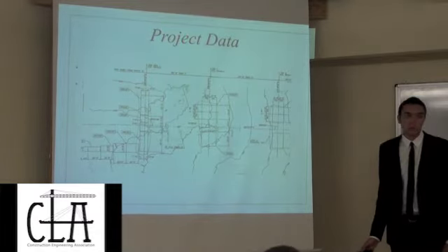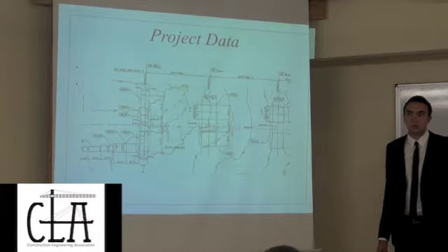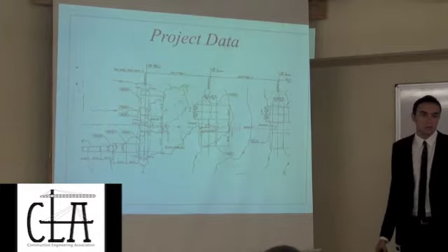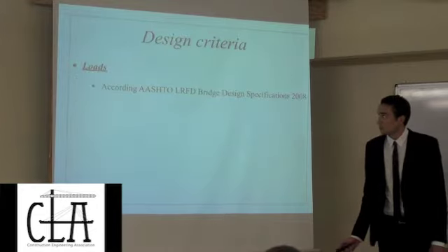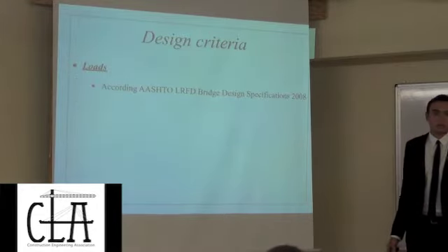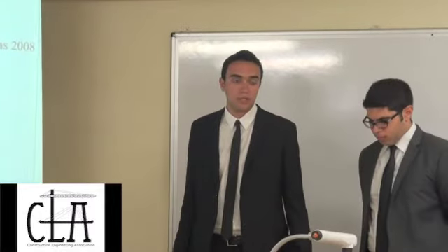The drawings also include some design notes indicating the codes used in the design and some of the design loads used for the original design. All of our analysis and design will be based on the AASHTO LRFD bridge design specification, as our design should and must satisfy the limit states: strength limit state, service limit state, fatigue limit state, and